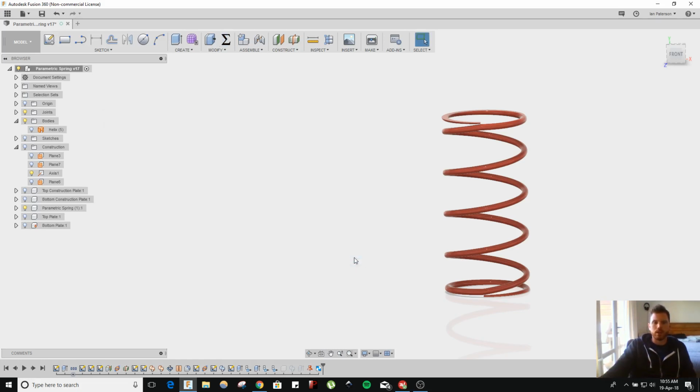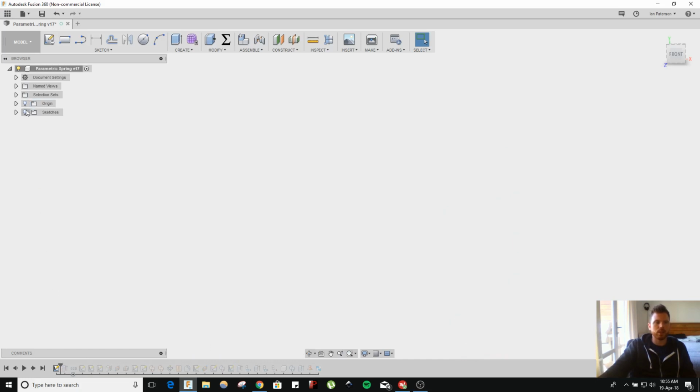Yeah, so I'm going to leave this as it is for now, and I'm just going to roll back to where there is almost nothing in this file. So if I roll back to my original sketch, I'll need to keep turning things on and off as I go because I've hidden lots of things.